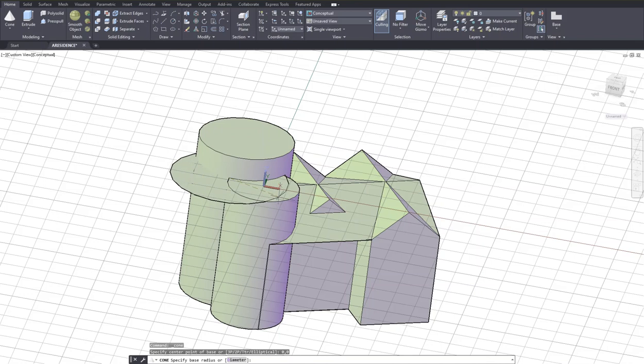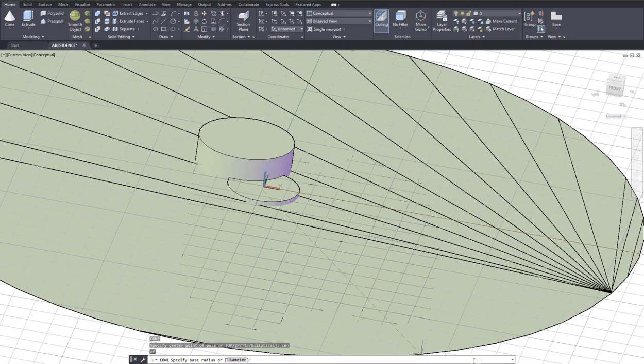And it did not turn out to be correct. I'm going to do this again. And I'm going to type CEN this time. Okay, I'm going to select, click. Now the cone is coming pretty much the way I expected. At this point, I do not need object snap.